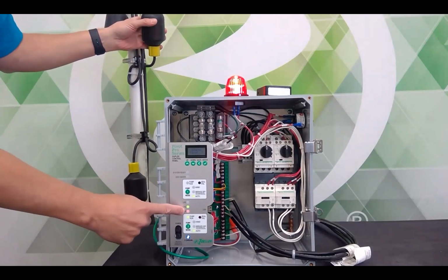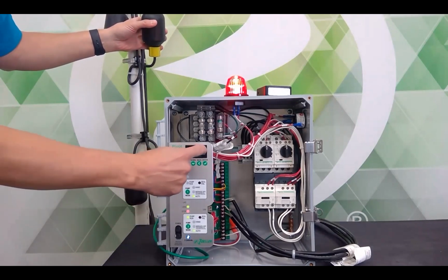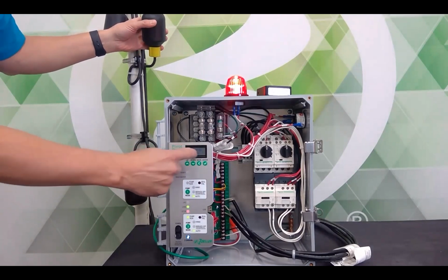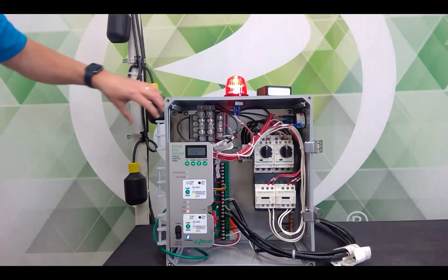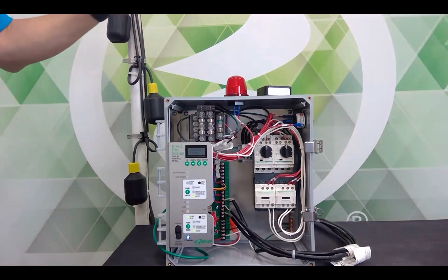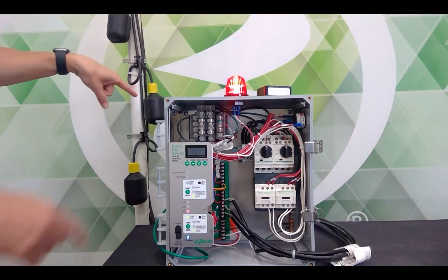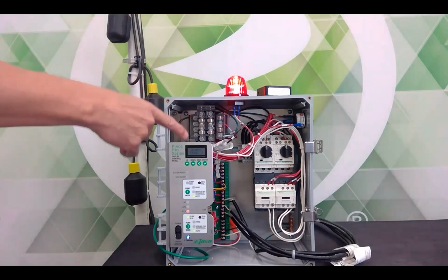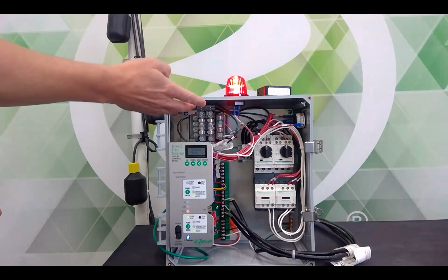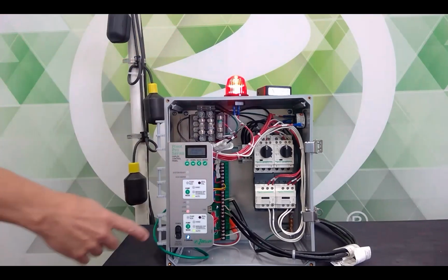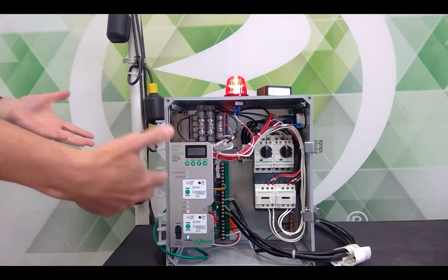I don't know if that comes through on the screen. And my LCD screen here says alarms, float 1. I let it down. These are narrow angle floats, so I don't turn it off immediately. I give it a 10-second runtime so that we don't short cycle pumps. And now I turn it off. There we go.